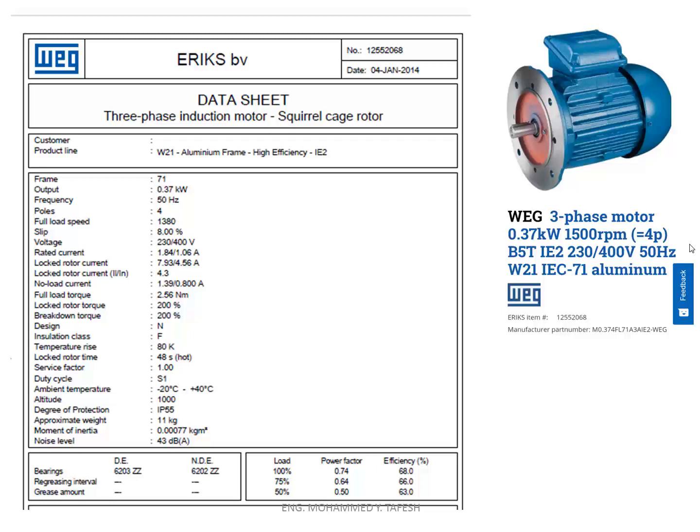When you buy a motor, you have to look for and write down very important parameters. You have to know the voltage system. You have to know if the motor you want to use is for 3-phase or 1 phase, and you have to know the frequency of the electrical network which the motor will work on, and you need the power of the motor.